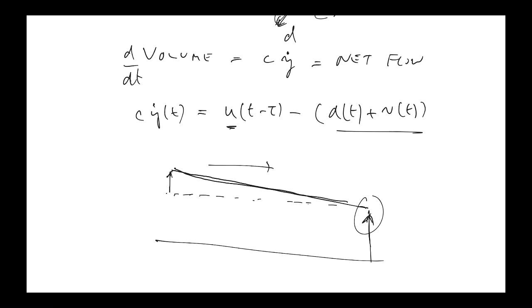We're not trying to regulate the water level all the way down. So we don't need a model that describes the spatial distribution of the water level along the channel. To do that, you need a much more sophisticated model. But this model matches very well the actual behaviour of this water level when you're changing the flow out and the flow in. Remarkably well.